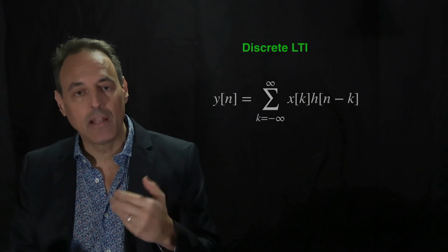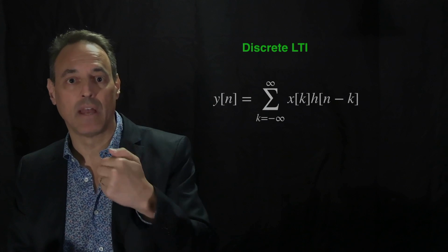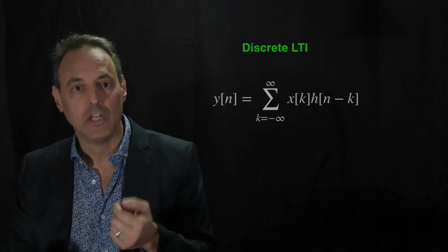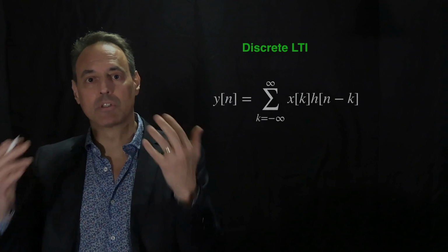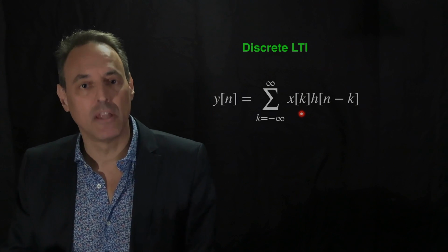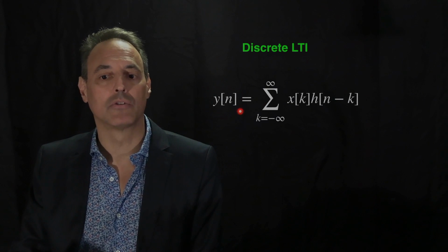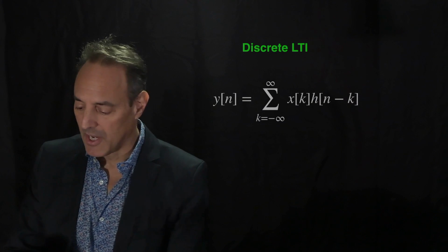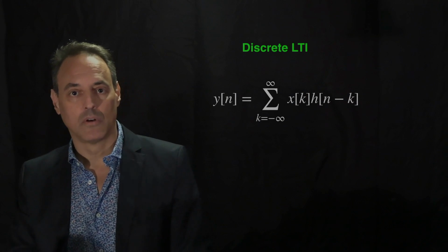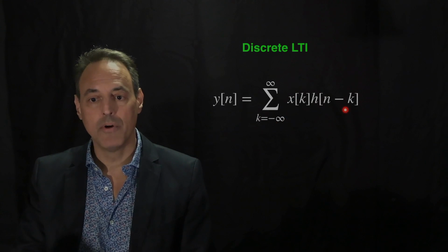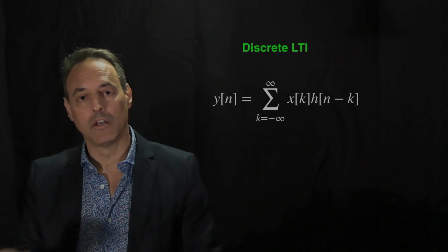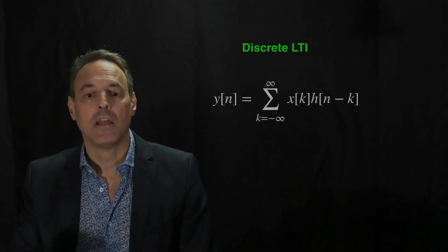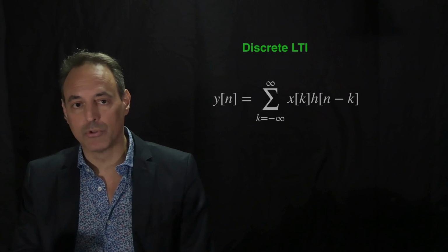And then to that, for instance, if I have a signal with some value at x2, I add the kick centered at 2. So I just keep summing up the responses to the different input signals, and that's how I construct the output signal. Okay, so this is a convolution. This is what this is called. It's a sum over all these, where I slide this thing here from k goes to negative infinity, infinity, and I add up all the contributions from all the kicks.